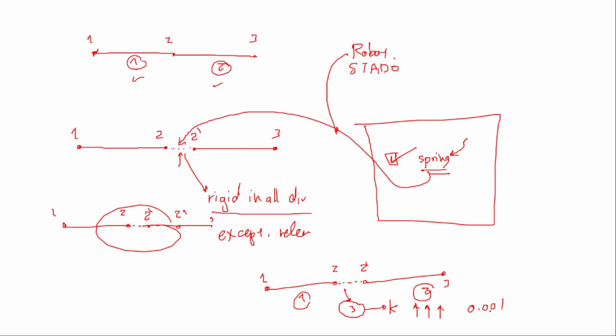Of course, I know that my Master of Science and PhD viewers are now face palming because they know that having a small stiffness value would have two effects. Effect number 1, it would introduce error because the stiffness matrix will cause some imbalances in your energy state, because this little stiffness will basically require some energy to rotate. And 2, it would introduce spurious mode shapes because you are applying artificial stiffness here. And 3, even worst case scenario, it could cause numerical instabilities in the condition number.